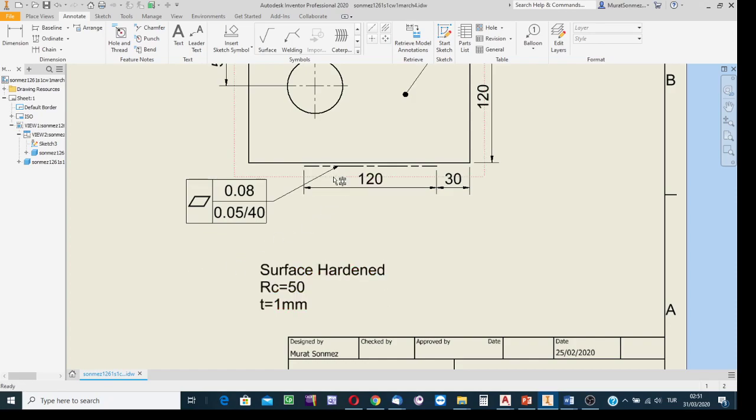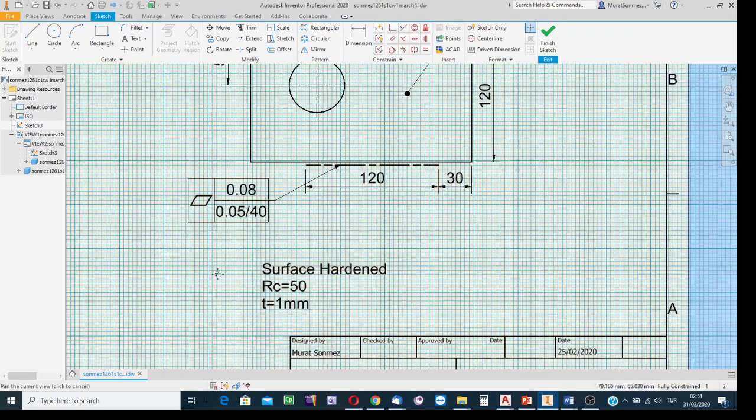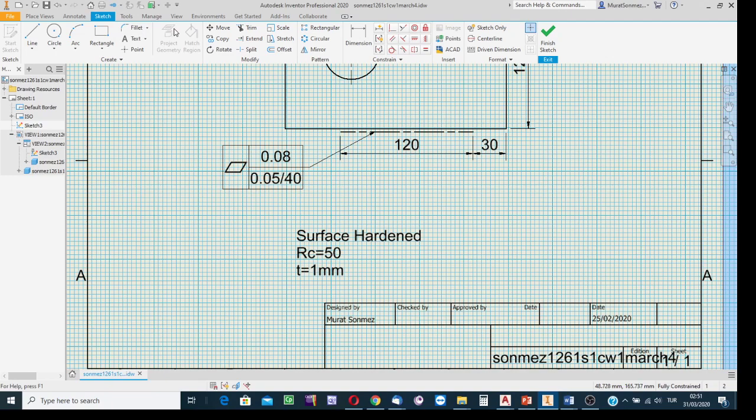To say that for the indicated one, one more chain line is needed. In sketch mode, if you forgot to add the other line, click on the start sketch button one more time and then make an arbitrary click on the page. No need to apply the projection process because there is no need to show any dimension or input any dimensional constraint. It is just a footnote marker.